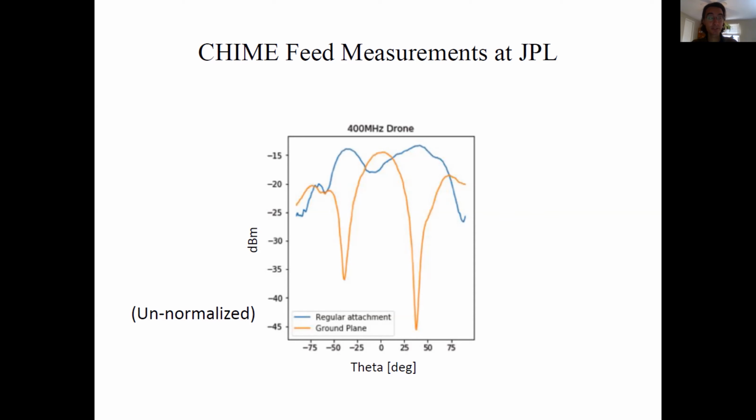The main difference between them is in the front end architecture. So CHIME uses these long cylindrical half pipe looking antennas, which were designed to be easy to have a large collection area. The problem that they're running into with that is that it's very hard to calibrate, because the antennas are all in a line down this half pipe, and so they're all coupled to each other, and you get a lot of crosstalk between them.